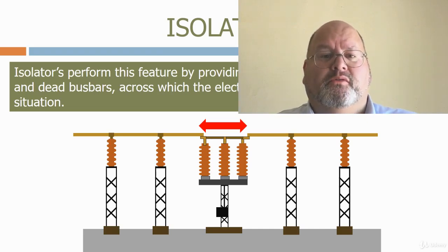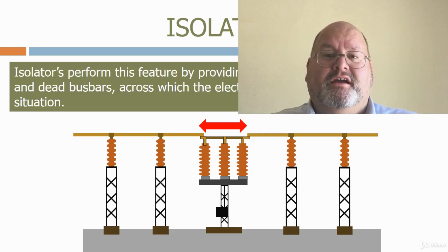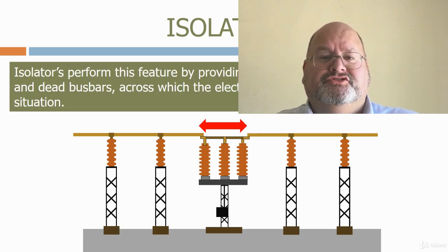Isolators serve an important role by ensuring that a circuit is dead and stays dead by the introduction of the physical gap in the conductors. They can also be locked off by a padlock or isolation key by the engineers. Work permits can then be issued based on their physical position.